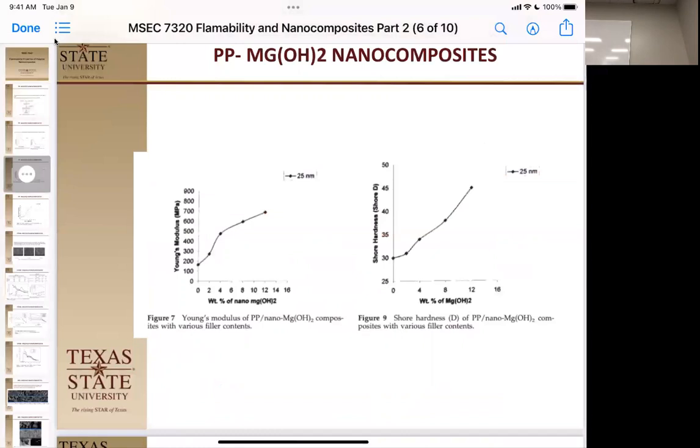But as all plates do, with some kind of constrained polymer theory, you do increase your Young's modulus, you do increase your hardness with this increase in material. Notice again, this is because the polymer next to that is not allowed to move as freely as in the bulk. So those little areas are, quote, almost a chemical cross-link that's making it tougher as far as your modulus and hardness go.